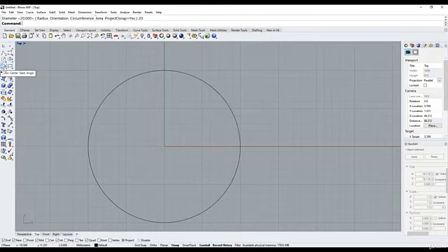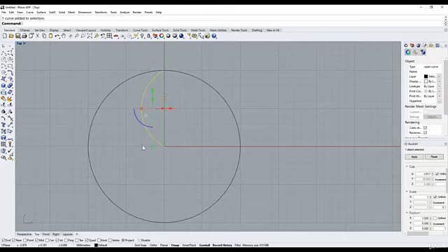So this is our arc menu here. If I cascade that out, this third one along, arc, start, end, direction at start. This is one I like using. So I'll select that. Our start of arc is going to be 0. I'm going to bring that up here, and I'm just going to bring that out to maybe about there. Okay, let's mirror that across.